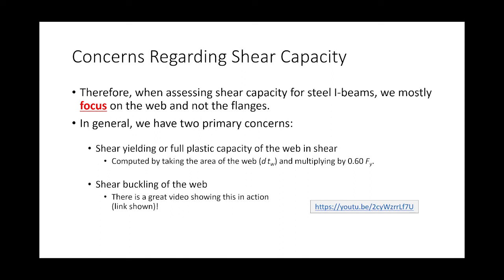Now what Mohr's circle tells us is that if you have an element under pure shear and you rotate it 45 degrees, you have tension one way, compression another. I seem to remember that things in compression like to buckle. So as we load this, boom, we start to get a shear buckle. That shear buckle occurs at around a 45-degree angle because that's what's going on in terms of our principal stresses. Does everybody kind of see this?